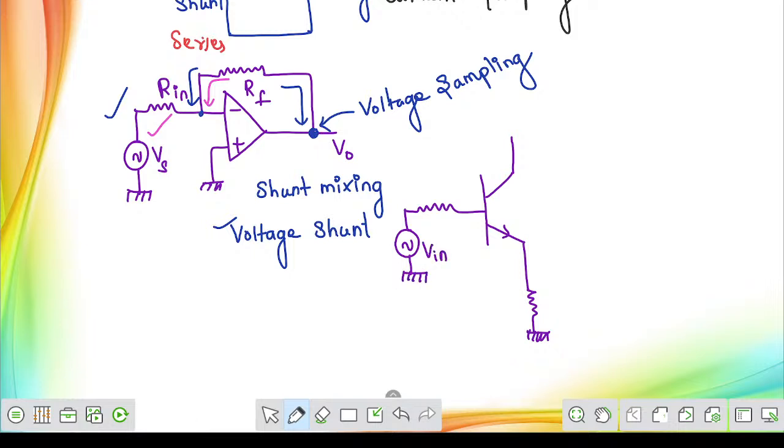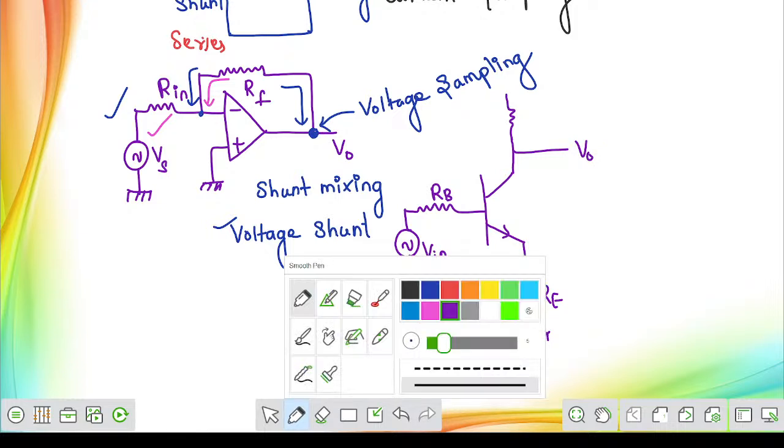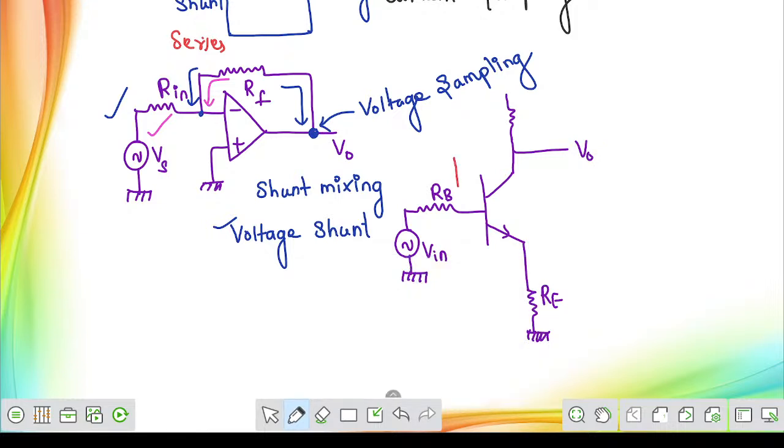This is the input resistor, let us assume that is the base resistor. This is the emitter resistor. Everything is clearly given. And here this is the collector circuit. They are measuring the output voltage at this point. Now, what they did here is, after doing all, they simply attached a feedback line between the input and output point, a common resistor which is connected here.